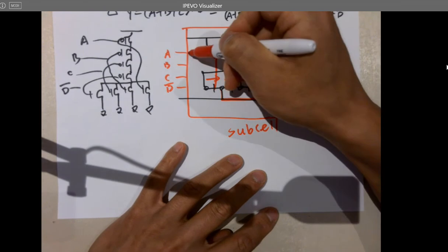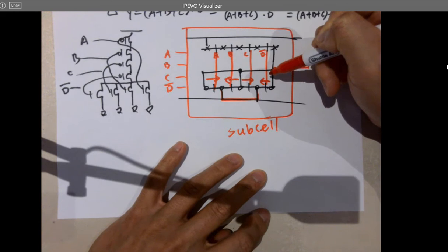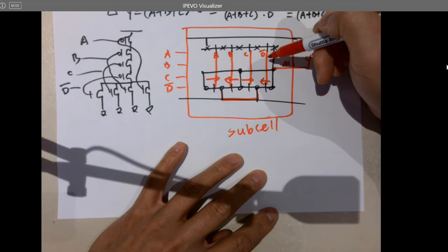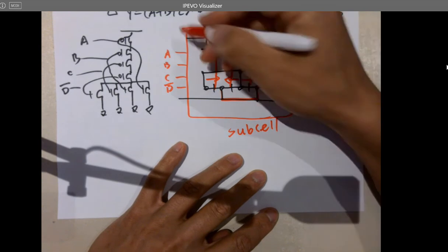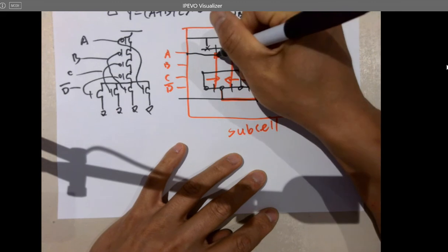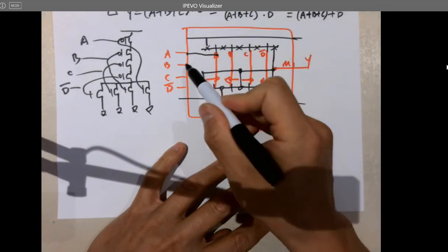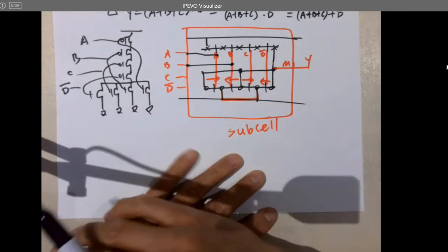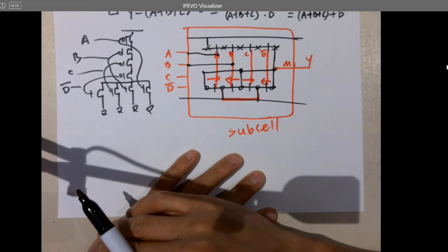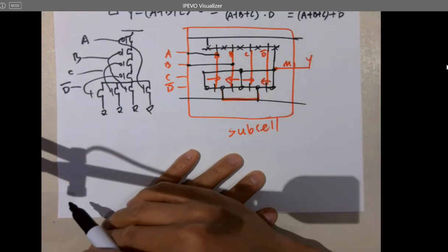Do you want to use polys, boom, boom, boom, boom, directly? No. It's shorting all the signals, right? You want to use a different layer. So just use metal one from here to here. Definitely it's fine because there's nothing in the middle, right? This one, still metal one. Does that matter? Is this causing any short circuits? It's not. This is poly. So you are good.